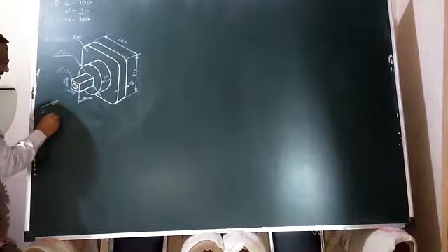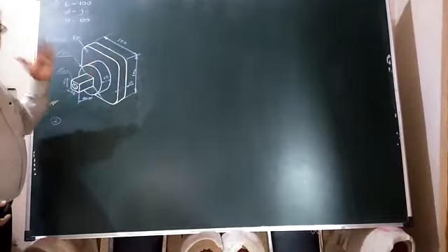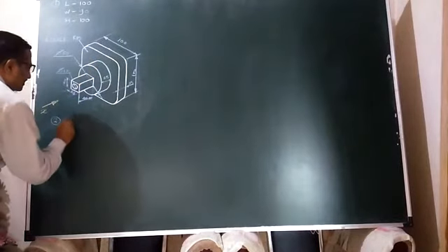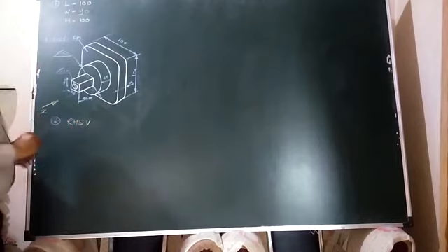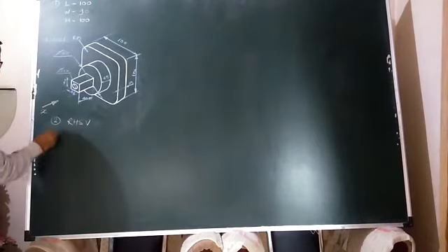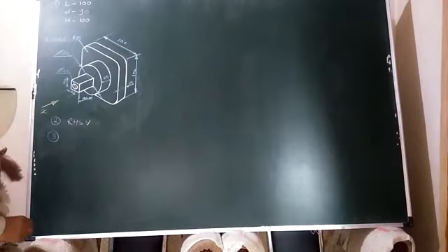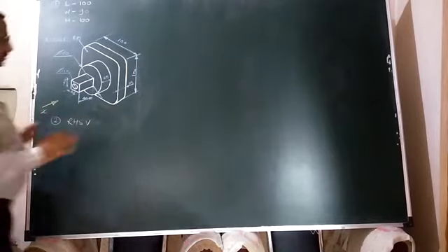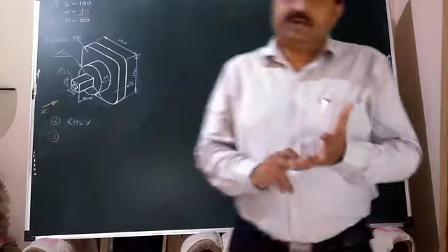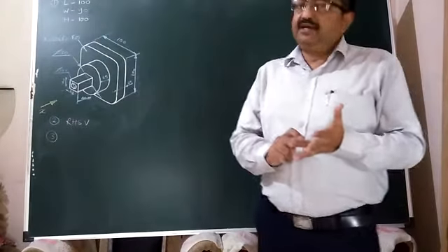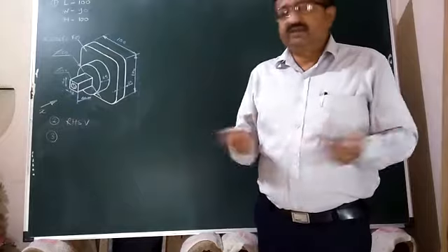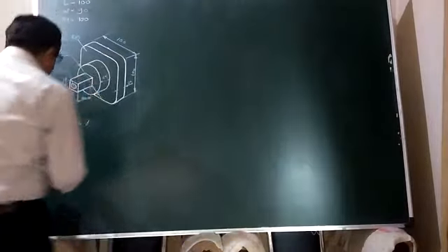Second point is which kind of side view is expected. Just now we have discussed, the left hand is busy for its front view. So naturally, the right hand side view is the expected side view from this exercise. Third, the overall areas of all the respective views. Front view needs L by H, top view needs L by W, and its right hand side view naturally requires only width and height. So accordingly we will note down the front view area, top view area and right hand side view area.